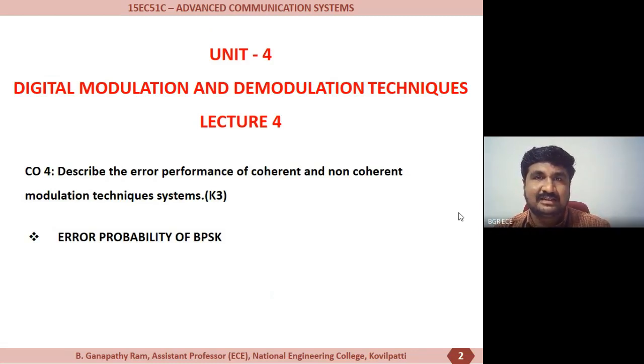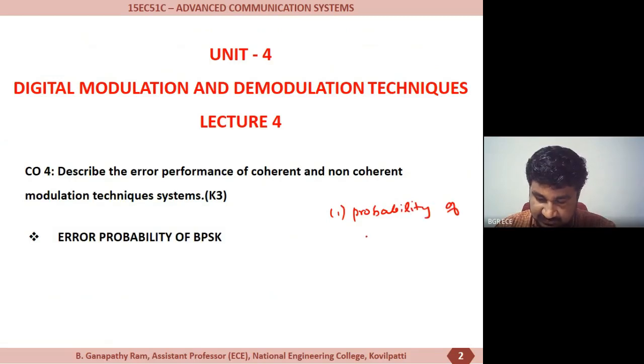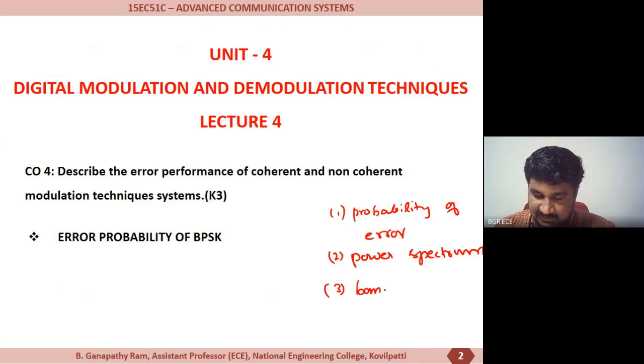As discussed in the earlier sessions, every digital modulation technique can be evaluated with some performance metrics. Those are probability of error, then power spectrum, and bandwidth efficiency.